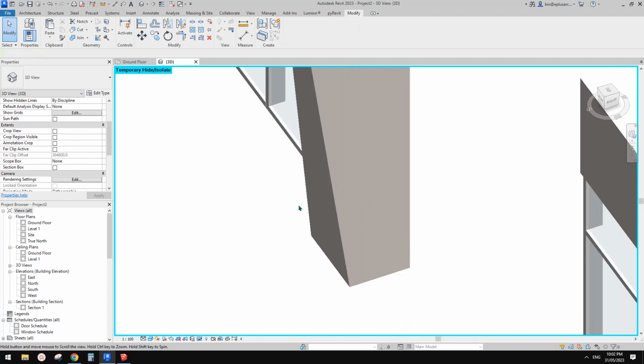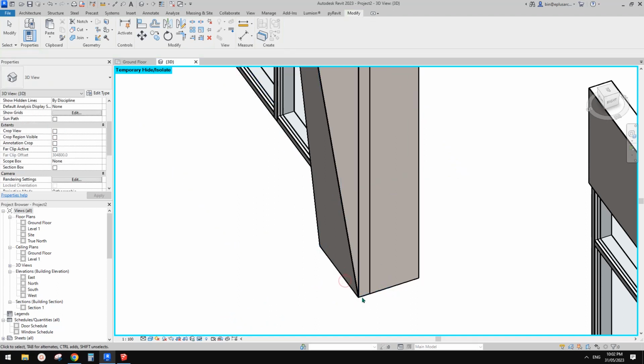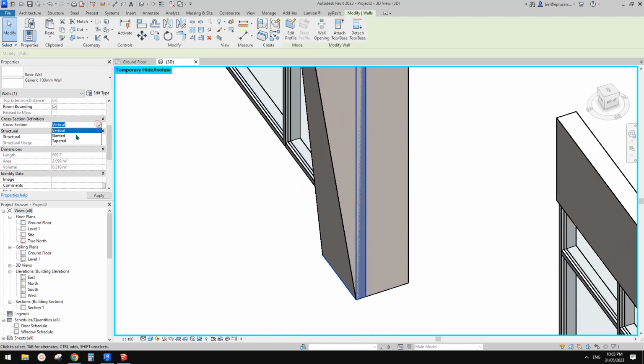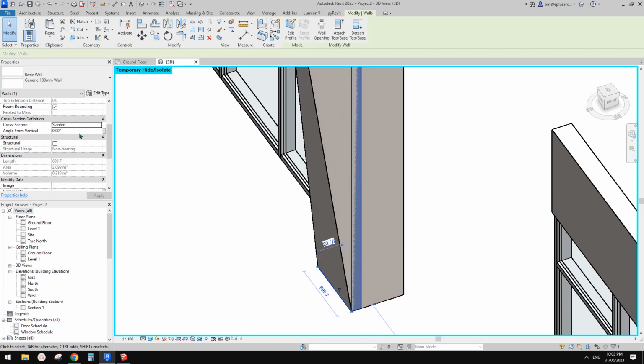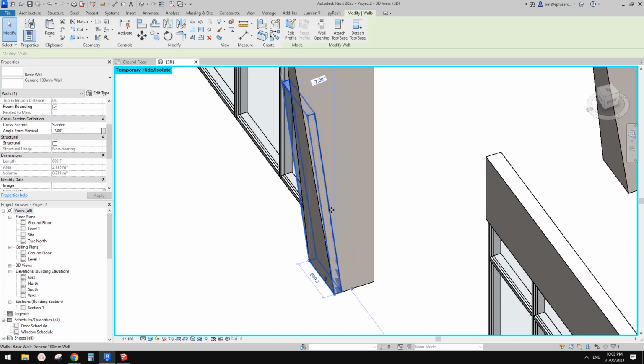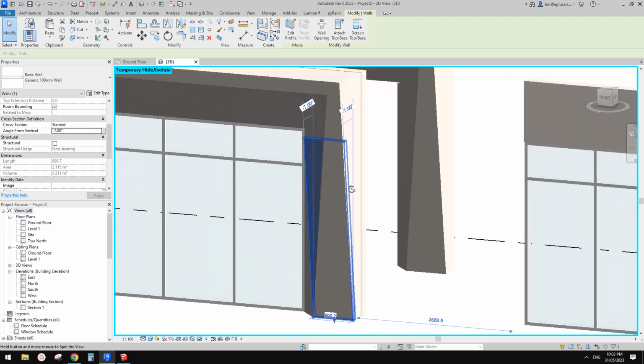So I'm going to delete it. So do it again, WA. I want to use finish exterior. So and then pick line, place. Yeah, that's better. So now let's change this one to slanted wall, and I'll just try 5 degree. The other direction, so I'll just try negative maybe 7. Yeah, so you can achieve this, but it can be quite hard to try.